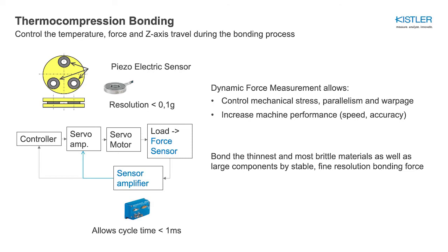The application here shows 3 sensors mounted into the bonder head, which allows to manage warpage and parallelism as well. The beauty of the piezoelectric sensor is the high resolution, smaller than 0.1 gram, good repeatability and compactness, which allows to perform closed loop control in real time.